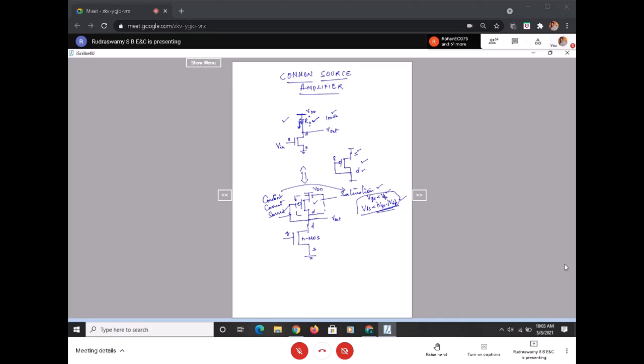Now I can say that the PMOS and this resistance are equivalent. Why is the passive component replaced by an active component as a resistance? So this particular PMOS is now acting as a resistance which allows a constant current to flow. In other words, this is acting as a constant current source now, which is equivalent to that RD. Hope this is fine with everyone.